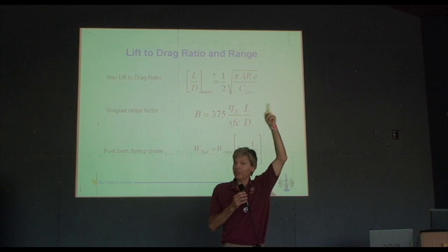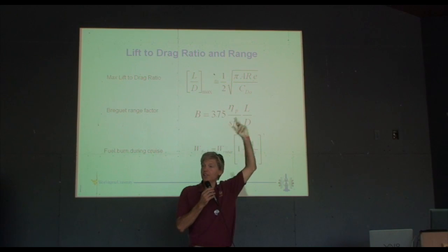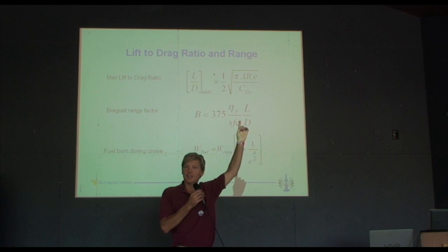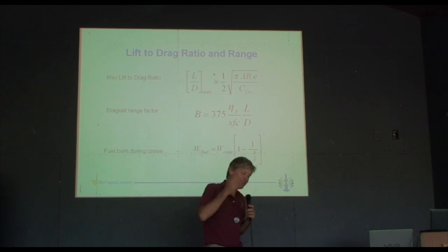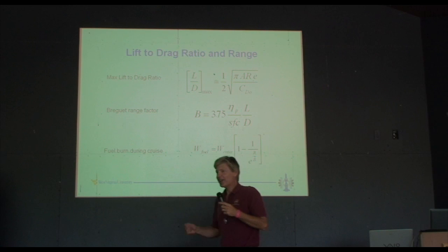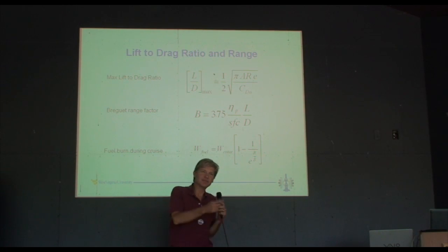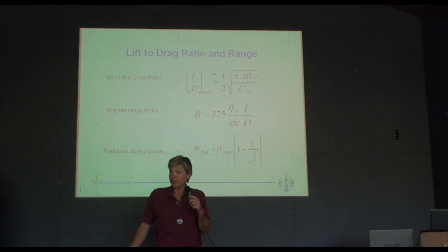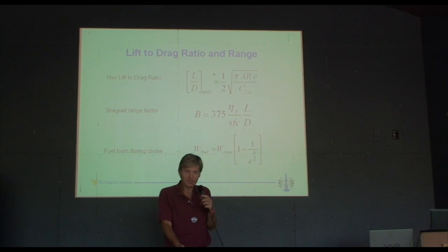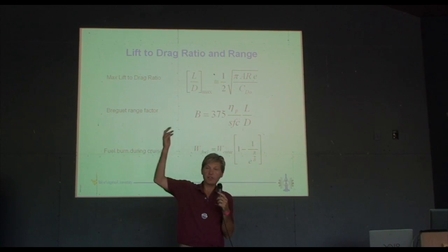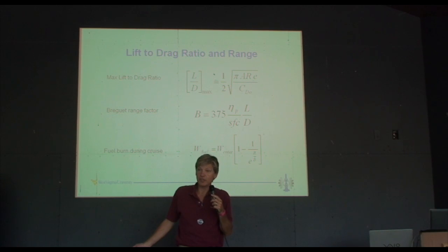But if we could get up there, we could fly at L over D max, 220 knots. Why do you think all the airliners are at 40,000 feet? It's so funny, everybody says airplanes fly high because the drag is so much less. I have to laugh. The lift-to-drag ratio for an MD-80 is 17.4. It's 17.4 whether you're at sea level, 1,000 feet below sea level, or at 35,000 feet. It's still 17.4.